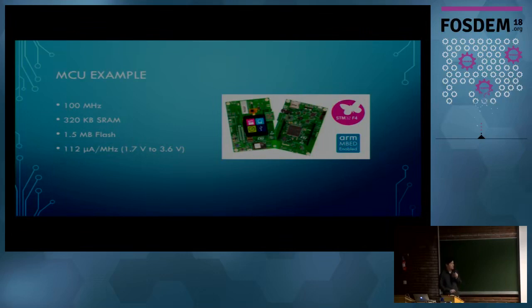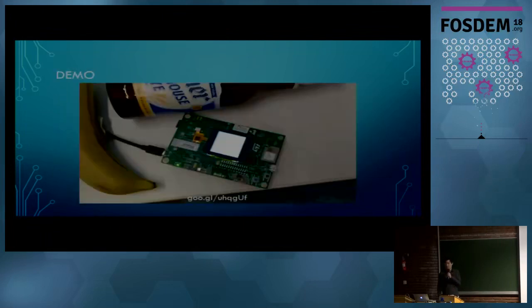It has a flash memory, but the most important thing here is the power. Some of those microcontrollers are meant to be run on coin cell battery for like months. So compared to running things on maybe PC, GPU, or cloud, personally, I think this is probably one of the most important differences here. It's the power consumption.